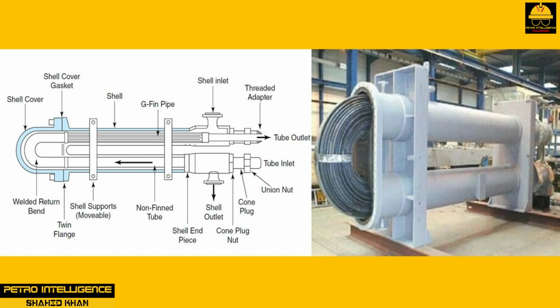The hairpin design has several advantages and disadvantages. Among its advantages are its excellent capacity for thermal expansion because of its U-tube-type shape, its fin design, which works well with fluids that have a low heat transfer coefficient, and its high pressure on the tube side. In addition, it is easy to install and clean. Its modular design makes it easy to add new sections, and replacement parts are inexpensive and always in supply. Among its disadvantages are the facts that it is not as cost-effective as most shell and tube exchangers, and it requires special gaskets.